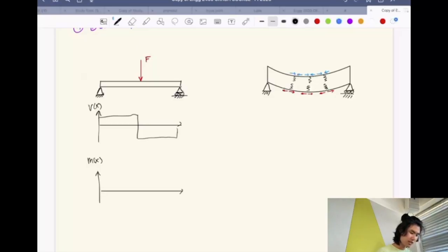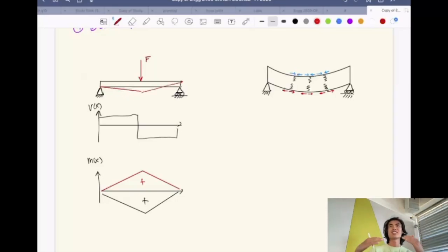So in civil engineering as well, it's more common to draw the bending moment positive on the negative side. Mechanical or other disciplines might put the bending here as a positive side because it just makes more sense. For us in civil engineering, it makes more sense to put it on the bottom because it's showing how the beam is going to bend in that way, right? Like if you were to see this beam, it will bend kind of like that rather than concave up.